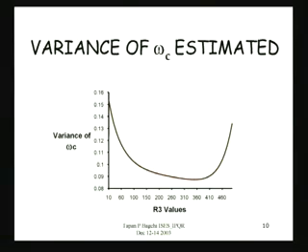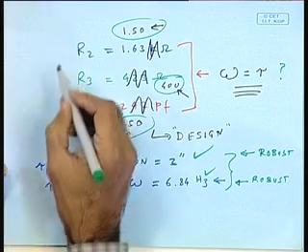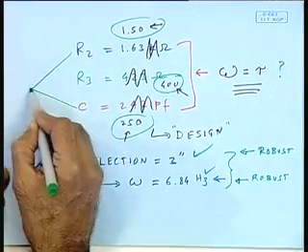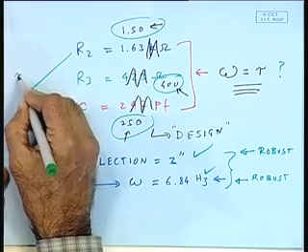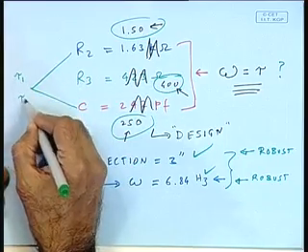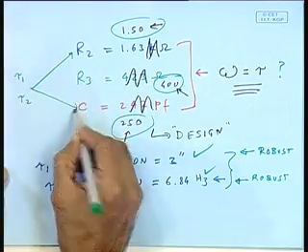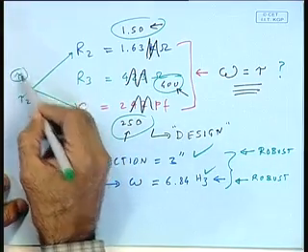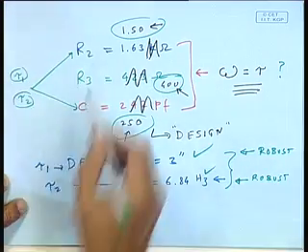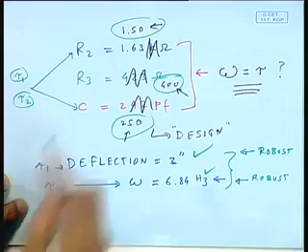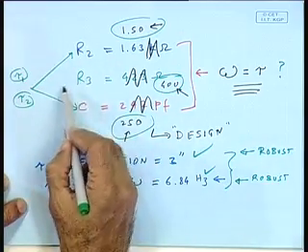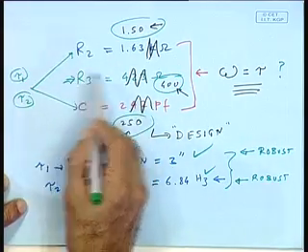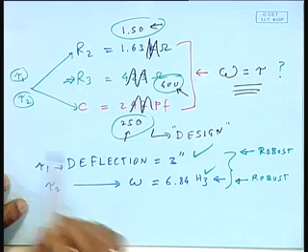Here what we've done, we've chosen R2 and C in such a way that we get the 2 targets, tau 1 and tau 2. Because these are simultaneous equations, I've been able to get this target and that target met by selecting appropriate R2 and C. The one that is left free is this one. This is the one I'm going to be manipulating to try to minimize variance.